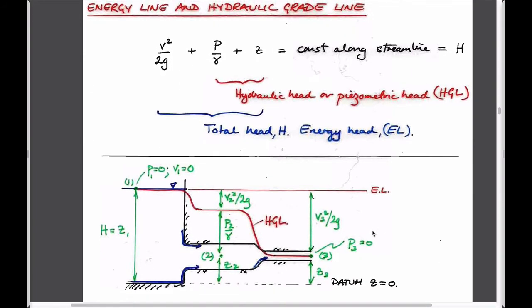So that's water pressure measurement, if you like. It's difficult typically to meter velocities exactly, but you can do it either in closed flow pipes by measuring pressure differentials, or in open flow systems, typically by measuring elevations. The whole concept of Bernoulli, to tie things up, is the fact that this remains constant along a streamline. We can call this the total head of the system. If we write it in this form, this is always in units of meters, or length.